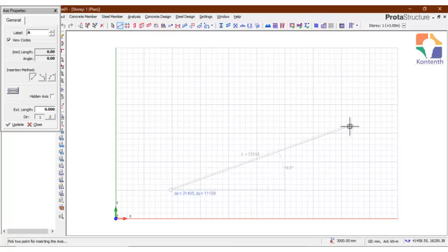One thing that I described in the earlier note is you can also tell it the length of the axis by toggling this value, like pressing F2. When you press F2, it locks in the measurement. So here it is asking you to tell it the length. Let's say it's 20 meters, so that will be 20,000 mm. Let's press OK.